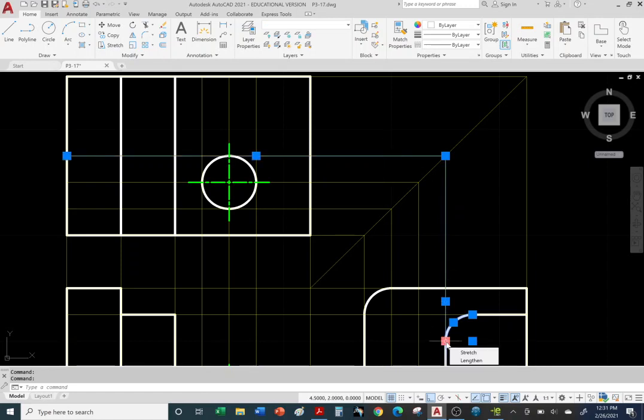So from this tangent point of the arc to the line, we're going to go straight up, hit the 45, go across, and we know that we're supposed to remove this bottom portion. So the line goes from here to here, right? Again, we project upward, hit the 45, so this is the 45, and we go across.